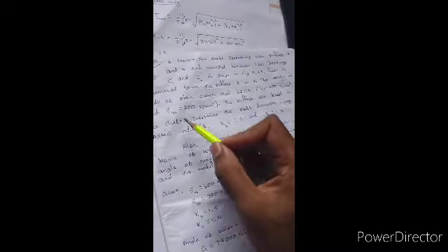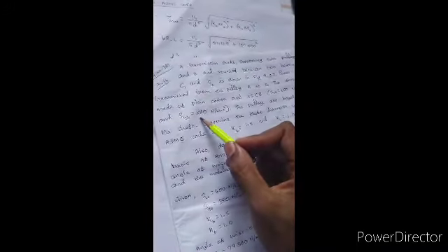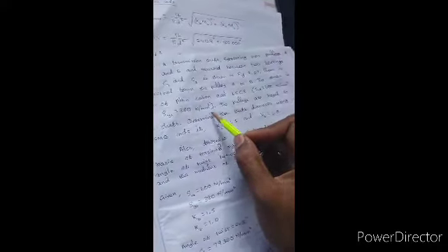Let me read the question again. So up to this we have read the question. Now power is transmitted from pulley A to pulley B. We have seen two pulleys are there, pulley A and pulley B. Input is pulley A, output is pulley B. The shaft is made of plain carbon steel 45C8 and ultimate stress is 600 Newton per mm square and yield tensile stress is 380 Newton per mm square.